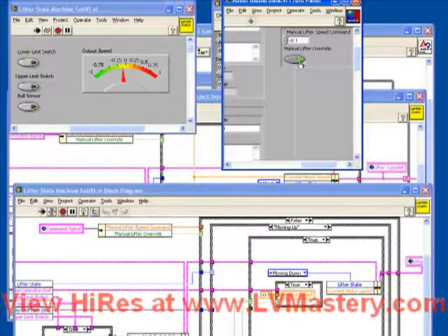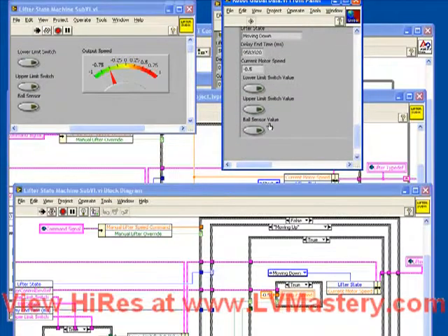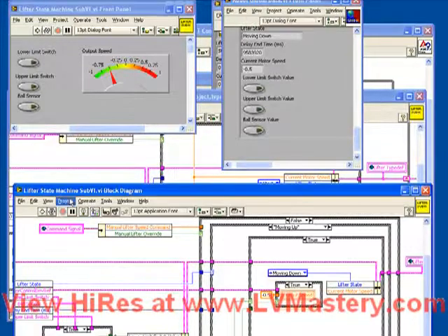And if we turn off our manual override mode, and then navigate back to this part of the shifter, we see we've gone into the moving down. Now we've actually gone to the start and then to the moving down case. It just happened so quickly that we couldn't see it. So this is a really nice way to test the logic of your state machines without risking damage to life or limb or to the robot.